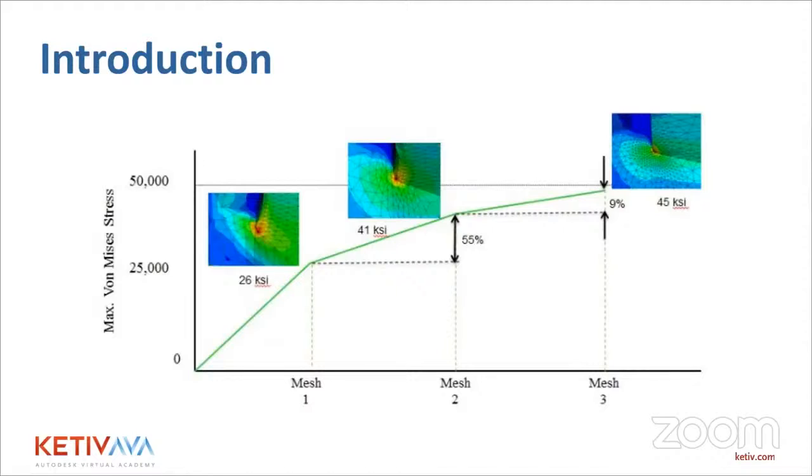Now, as a general rule of thumb, a higher element count is going to lead to greater solution accuracy. In most problems, however, refining the mesh beyond a certain point leads to very small, if any, changes in solution. This convergence is one of the primary means of actually verifying the results of an FEA study, and we'll look at that shortly.